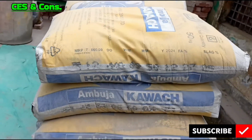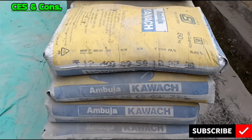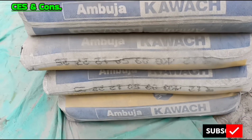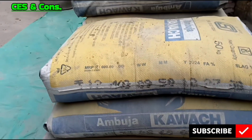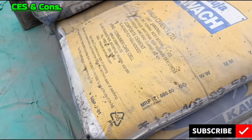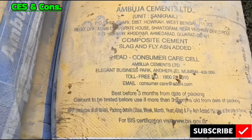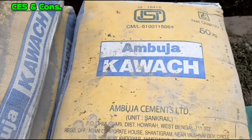Number 1. Ordinary Portland cement. This is as per IS 269/2015, grade of which 33, 43 and 53 grade. Generally used OPC 43 and 53 grade. Number 2. Portland Pozzolana cement. This is as per IS 1489 Part 1 and Part 2, 2015. This cement is fly ash based or calcined clay based. This is widely used in RCC due to durability, low heat of hydration and economy.